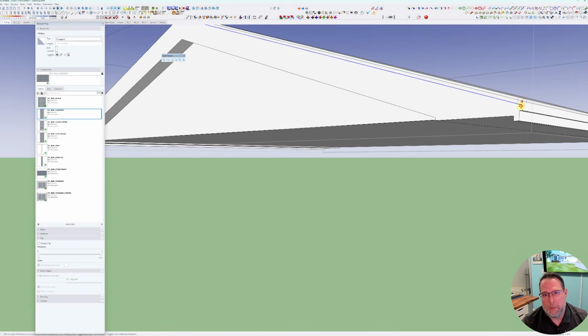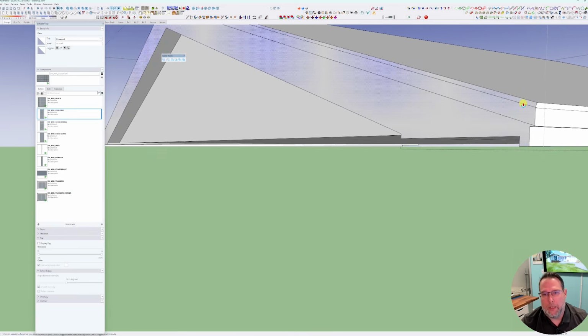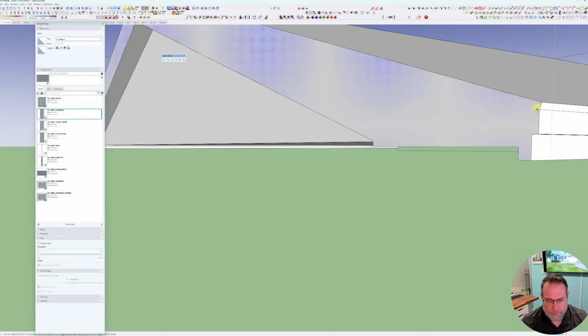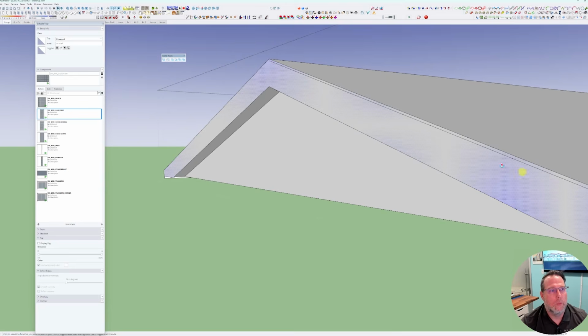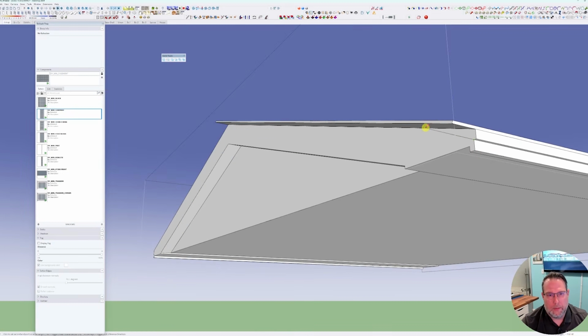And I'm just going to do this quickly, even though this might not be fully accurate. I would get into a whole other level of modeling the gables, but I just kind of want to show you generically what this might look like. And I'm just going to do the one side. Just push-pull this up, or extend that line, and then we can push-pull this out, however long, maybe it's 8 inches to there, and then we have,